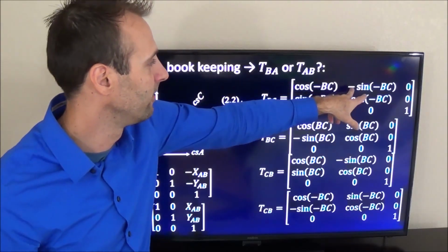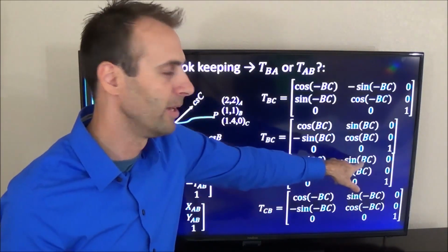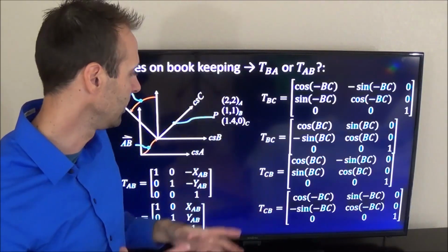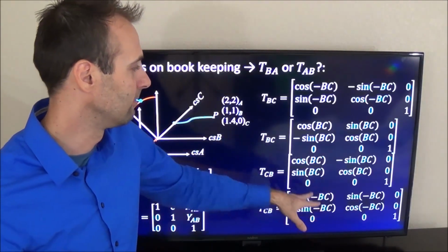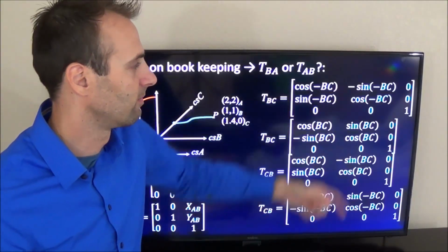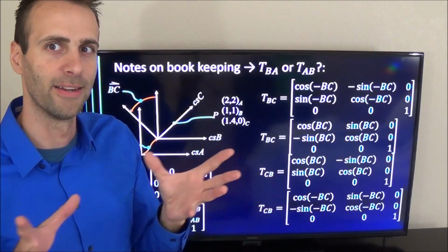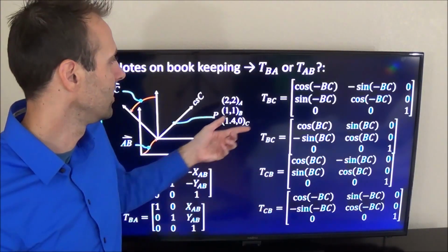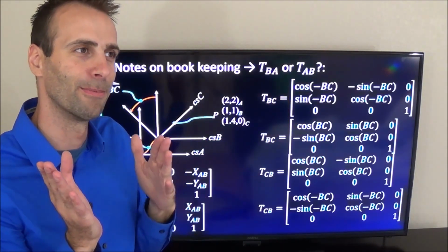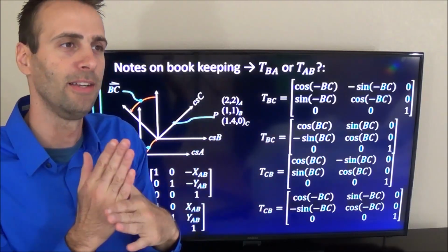Okay, but to get rid of this minus sign, I go from C to B, but I measure from B to C. So you're measuring opposite of the kinematic chain, and it condenses the math a little bit better, but you lose these minus signs. Because remember, for a machine that's more right than wrong, these errors are going to be very small. So is it minus 1 degree or plus 0.1 degree? You can't see that.